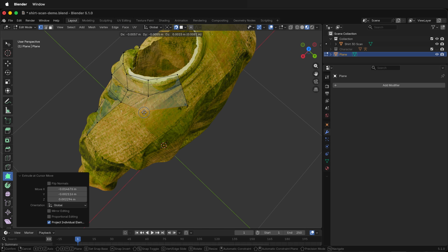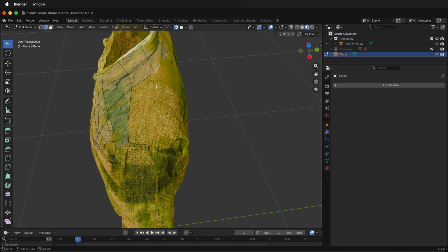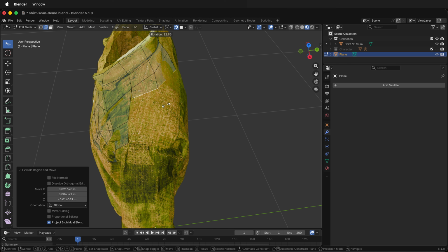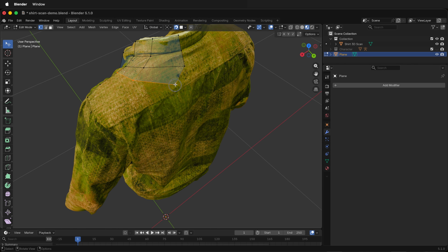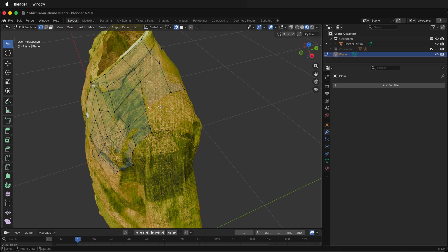And then now I can have both of these start to come over, but this is a little thick, so I'll just move these in. Then I can grab these 2 edges, press E, R to rotate them around, and this will start to make this flow over from the collar. Remember, we'll be adding much more subdivision. We just want to get the big parts.